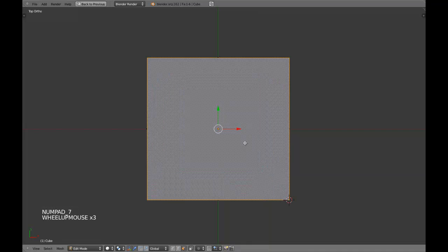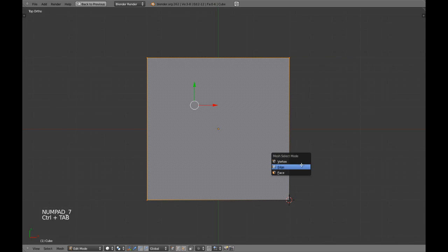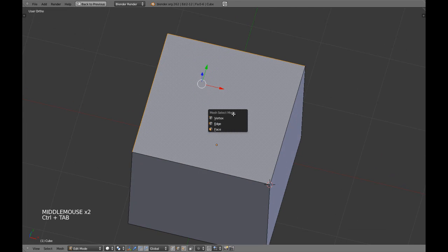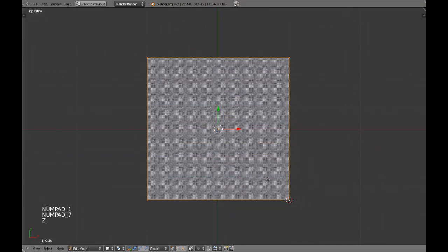You could change the pivot point of this face right here in the pivot point options. By default, this comes as median point, and I will show you that this is the midpoint that is usually changing depending on your selection of things.